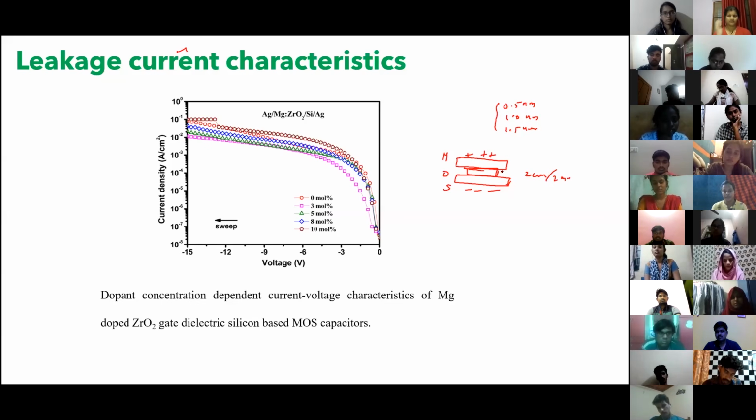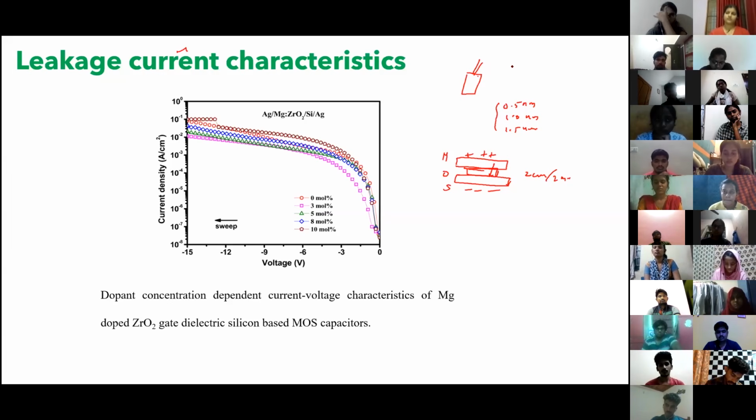So when you reduce the thickness to a few tens of nanometers, the material is susceptible to leaking some charges through that. It won't behave like a perfect capacitor that you used to see, like a cylindrical capacitor with 2 leads. Once you charge it, it won't leak normally, because the thickness of the layer is quite large in regular capacitors.